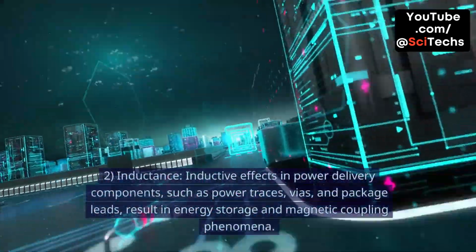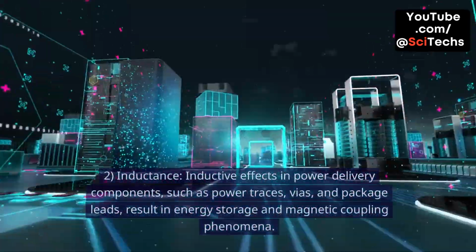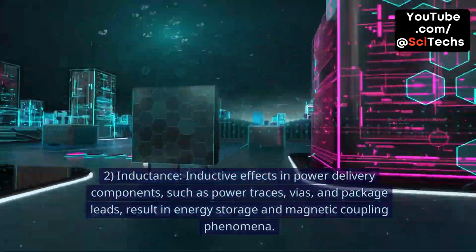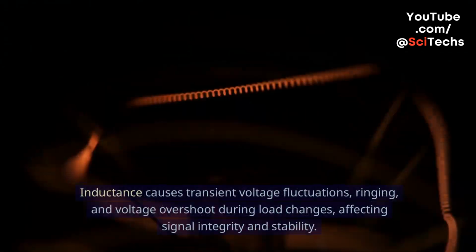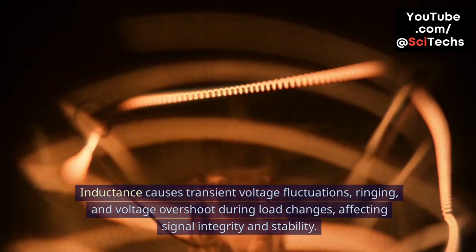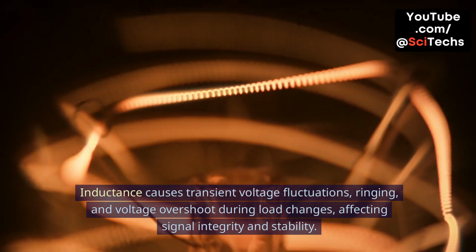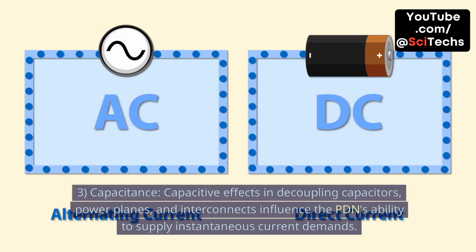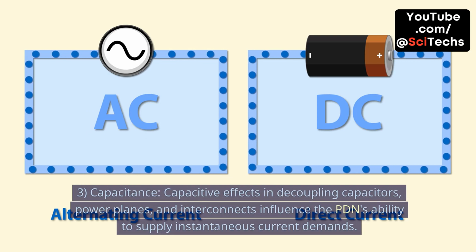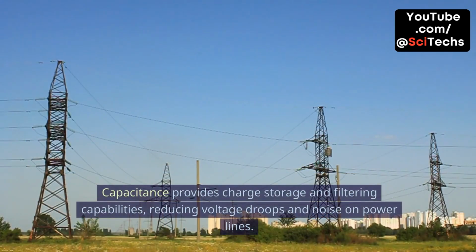2. Inductance. Inductive effects in power delivery components, such as power traces, vias, and package leads, result in energy storage and magnetic coupling phenomena. Inductance causes transient voltage fluctuations, ringing, and voltage overshoot during load changes, affecting signal integrity and stability. 3. Capacitance. Capacitive effects in decoupling capacitors, power planes, and interconnects influence the PDN's ability to supply instantaneous current demands. Capacitance provides charge storage and filtering capabilities, reducing voltage droops and noise on power lines.